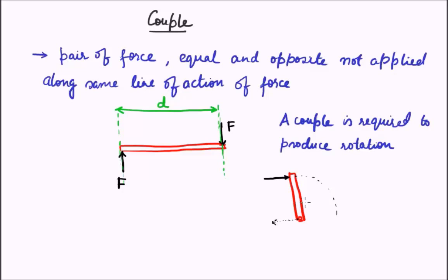You apply a force on the doorknob, and the hinge is like the pivot here, which creates an equal and opposite force, and the force at the doorknob and this force created at the hinge form a couple and lead to the rotation of the door, resulting in the opening of the door. Well, now we have some qualitative idea about couple, and we discussed some examples representing couple.